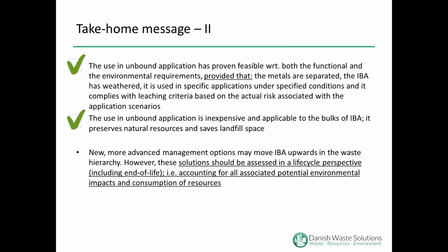The use in unbound applications specifically has proven feasible worldwide, as both the functional and environmental requirements are okay, provided that the metals are separated, the bottom ash has been aged or weathered, and it is used in specific applications under specified conditions.